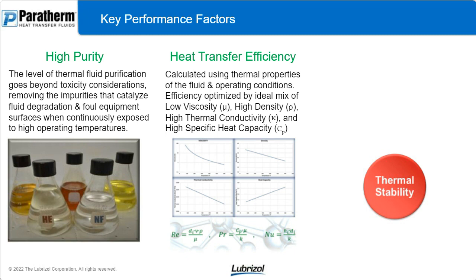Again, a really key point to point out here: it's not just about energy savings with efficiency in a heat transfer fluid. When you're talking about heat energy being transferred, any inefficiencies in that ability to pull that heat and transfer it will go into breaking the fluid itself down and degrading the product. That energy has to be used somewhere. So any inefficiencies will go into degrading the fluid.